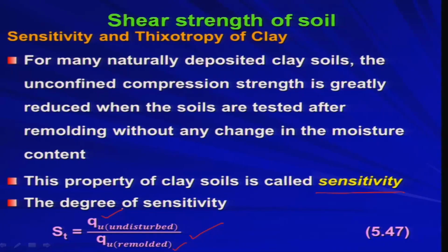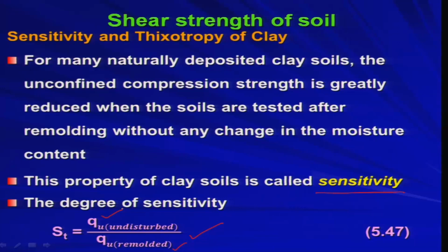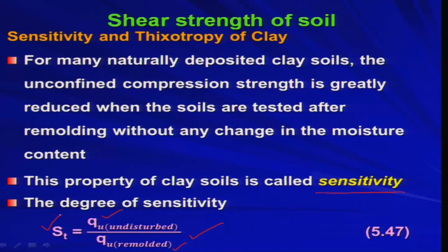Maybe you can go for the vane shear test. And for qu remolded, you can go for a triaxial test or an unconfined compression strength test to get this qu remolded value. The ratio of these two will give you the sensitivity.